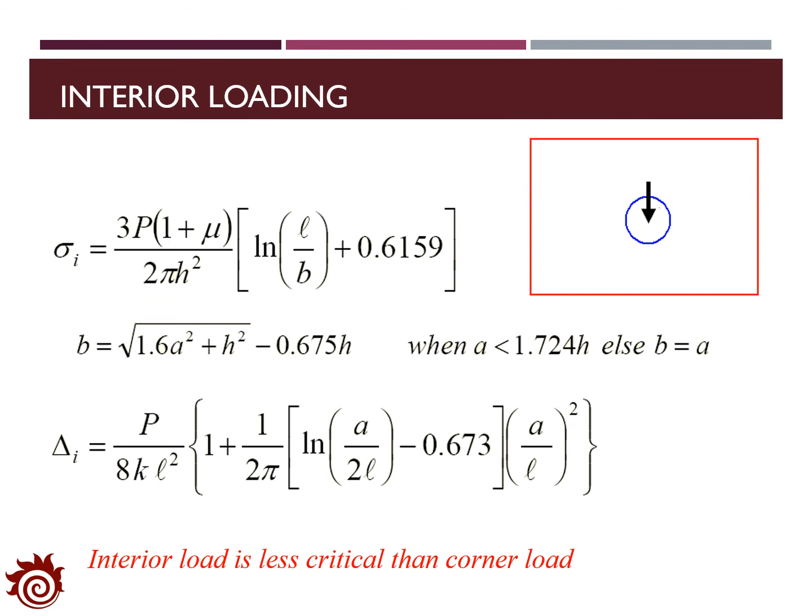Westergaard also proposed equations for the estimation of the stress and the deflection based on interior load, where the load is applied at the center of the PCC slab. The figure here shows the interior load.